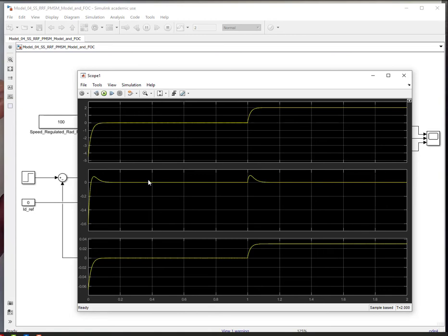Okay, and then you can also see here the d-axis response is regulated to be 0, and during that transient state we have cross coupling, right? Remember, we saw cross coupling between the d and the q axis. Due to that nature, you see some transient. However, since we have a closed loop controller on the d-axis, that is being suppressed by injecting additional voltage into the q-axis of the motor, and that's driven to 0. So now we actually get very nice performance from our system.